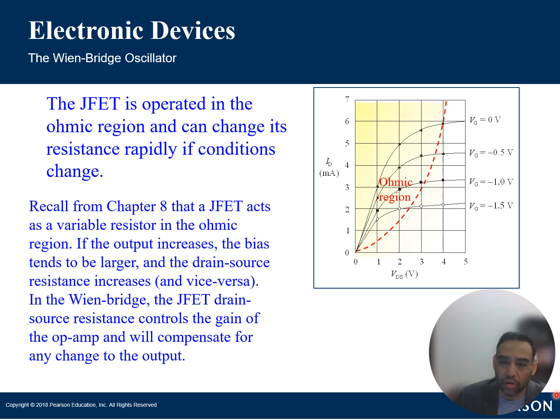So you can see we get this automatic gain feedback control through the JFET, and it can be extremely precise versus the image that you saw in the previous slide, and you'll see again in a couple more slides, where you have what looks like a schematic symbol for a potentiometer, and you don't really want that. So JFETs are awesome. Looking at the drain to source voltage, the drain to source voltage plays a role in the JFET operation. So again, when we're in the ohmic region, it should be kept sufficiently low to maintain the JFET in that linear operating region.